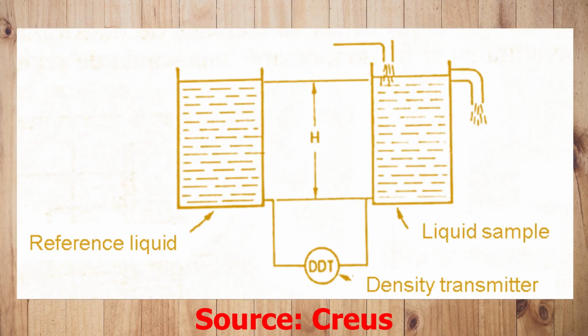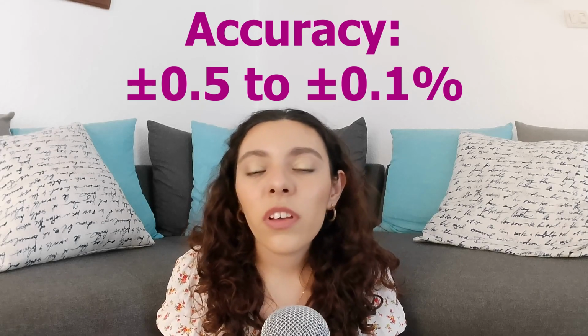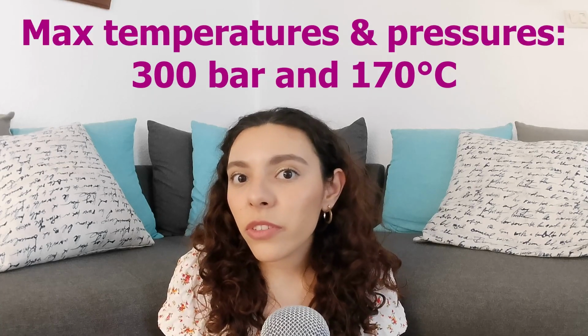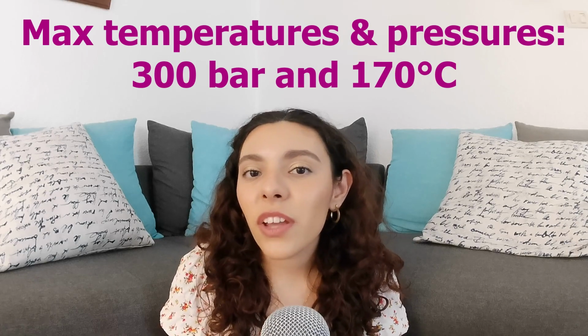In another system used in atmospheric pressure measurement chambers, the lower pressure branch of the instrument is filled with a liquid of constant height, which serves as a reference, whose density may be greater or less than that of the process liquid. These differential pressure instruments have an accuracy of plus minus 0.5 to plus minus 0.1%, and can work with pressures and temperatures of 300 bar and 170 Celsius degrees respectively.